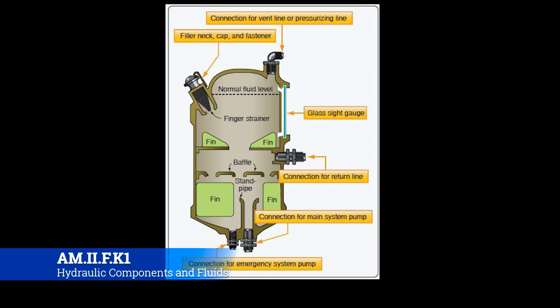Whereas with a pressurized system, you'd have to put pressure onto it, let the air out, close it really quick, and then keep putting pressure on, and you keep doing that over and over again. That's what bleeding the brakes is, and we're going to talk about that a little bit more as we get into this. But that's the advantage of a non-pressurized system.